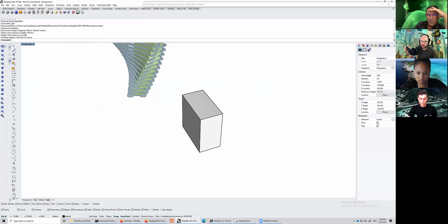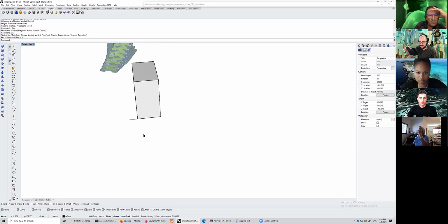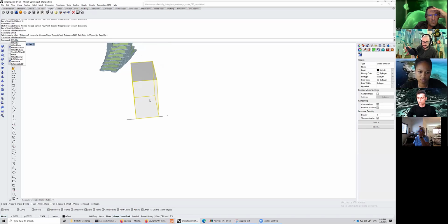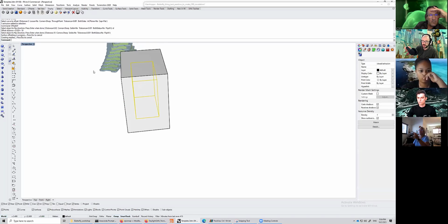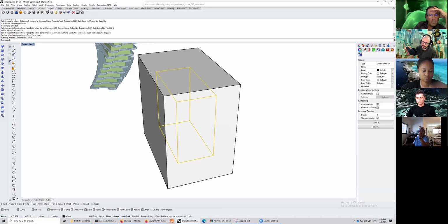What can we do? Well, we can say take this surface here, and in the first 5 meters, let's say around it, or let's say 10 meters, from this side and from this side, and if I can offset the surface, so what we say is we can tell OpenFOAM, from here and 10 meters outwards, imagine it as a bounding box extending, refine more than what you do outside of here.